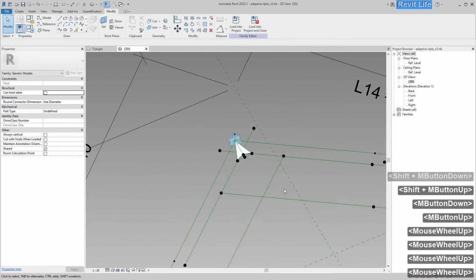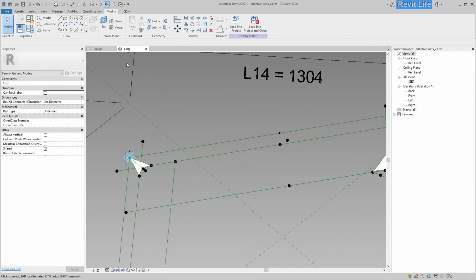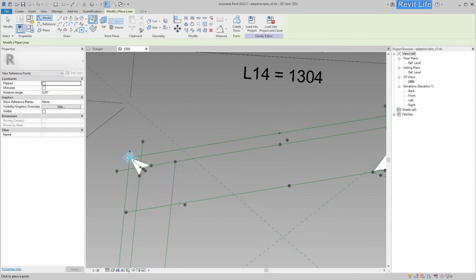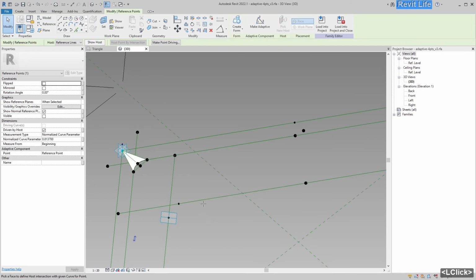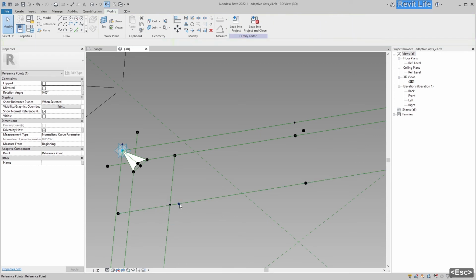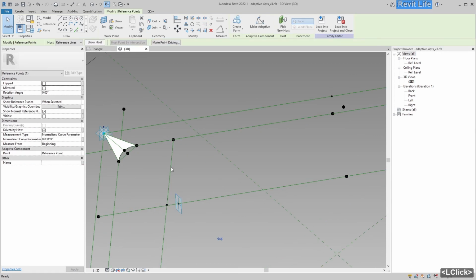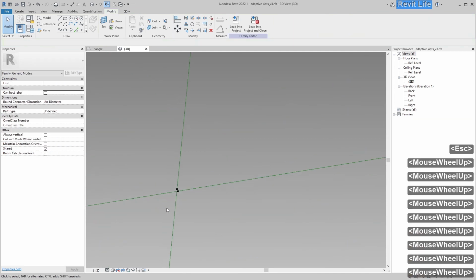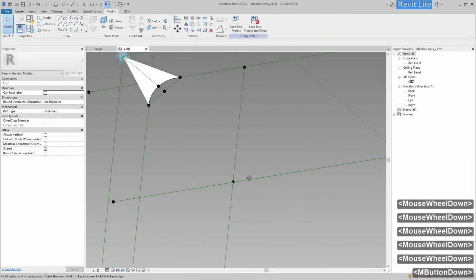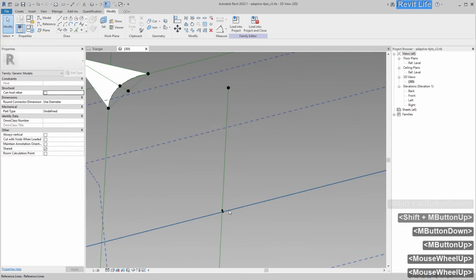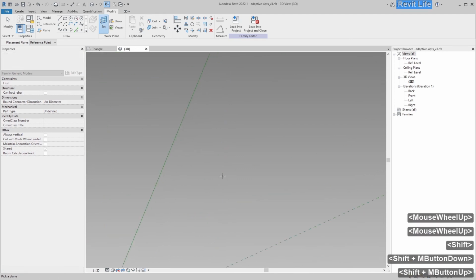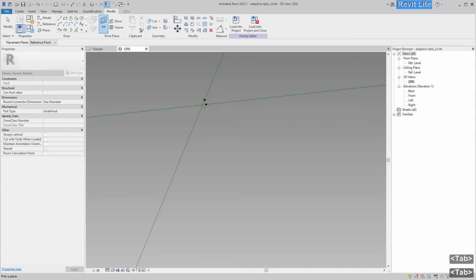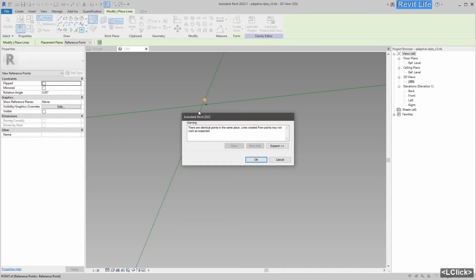Now, the last corner, we need to do exactly the same things. Okay, add 2 points. Select the first one, host by intersection. Okay, select the second one, host by intersection. Let's zoom in a little bit so we can see better. Okay, add points, set work plane. We need to see exactly, is this the right work plane? So okay, let's set this one.